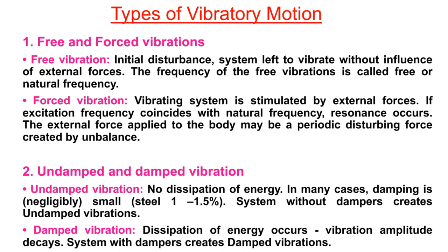Now, if the excitation frequency matches with natural frequency, there will be resonance occurring in the system. During this forced vibration only, resonance occurs. Due to external forcing frequency matching with natural frequency, there will be resonance. Remember this. This is regarding free and forced vibration. This we are going to study in detail, what is free vibration, types of free vibrations once again. But this is basic free and forced vibration.